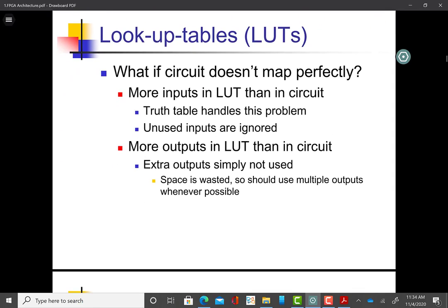So this is how it basically works. If the circuit is large, you divide it into smaller pieces, and each piece should be such that it can be housed in your lookup table. If you have fewer than the maximum number of inputs, for example your circuit has 2 inputs, then one of your lookup table inputs is unused, and you can deal with it by appropriately configuring your lookup table.